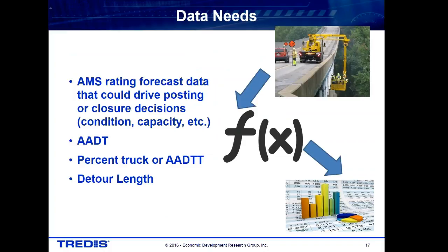Your agency will also have to determine a consistent means for identifying potential years of posting or closures of facilities under different funding levels by using various asset management systems and tools at your disposal. Some agencies have used predicted superstructure condition ratings, which are associated with postings and closures at their lower levels, or agencies may develop other rules based on current management practices.